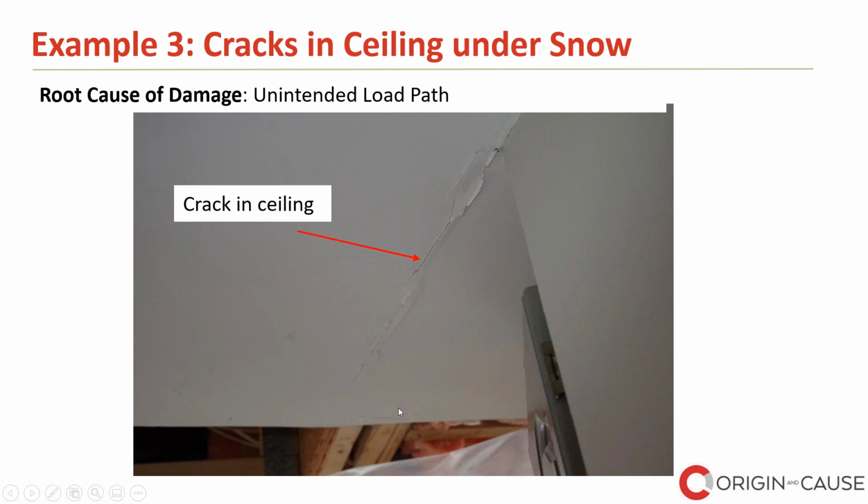So when you add rafters to the top of the trusses, the owner or the engineer had to properly connect the trusses together, so you have some continuous rafter tie and ceiling joist here.